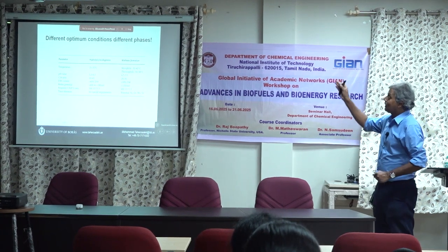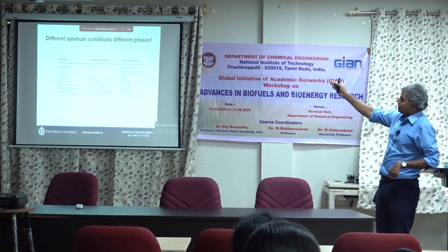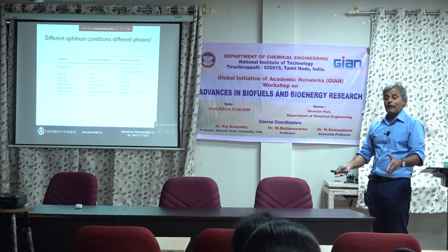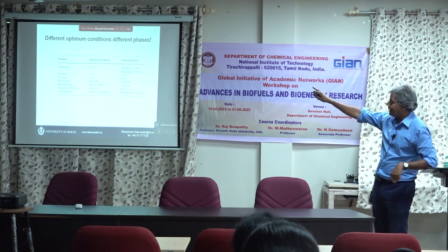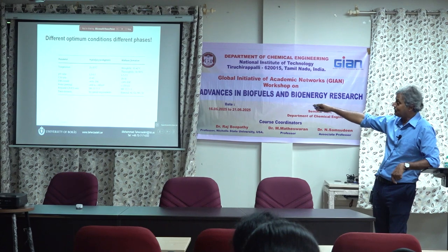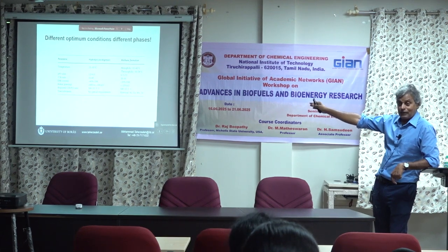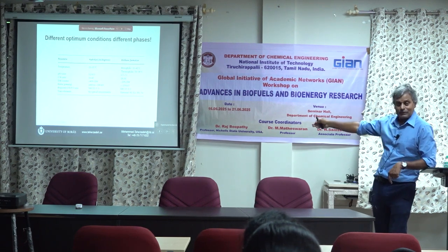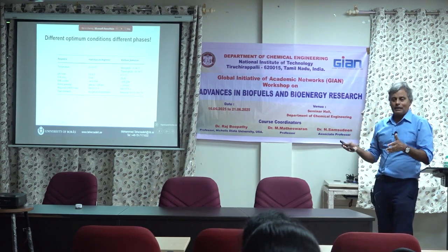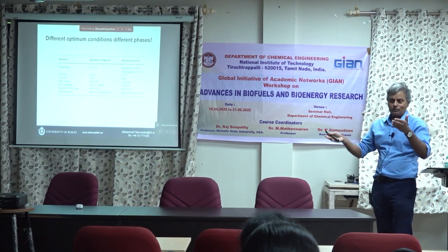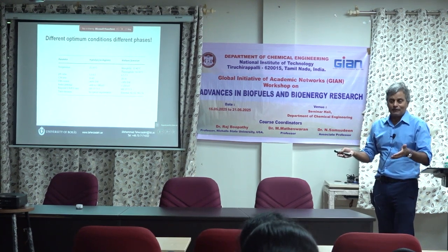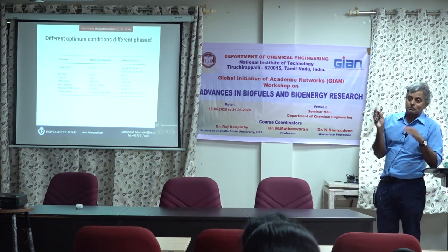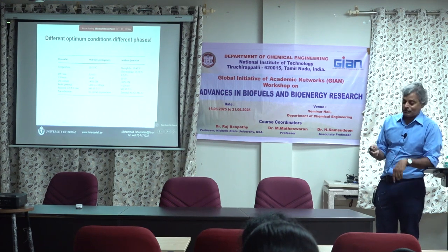So individually, if you want hydrolysis and acidogenesis to work at the maximum level, because your end product you want only fatty acid, you don't want methane, you have to create that optimum condition, temperature and pH, listed for that reaction. But if your end product is methane, you have to keep that condition. If you want to keep both in one reactor, you give a range, so you satisfy both groups in one reactor. Okay? So if you want your end product to be only fatty acid, you just prefer that bacterial dominance in your system.